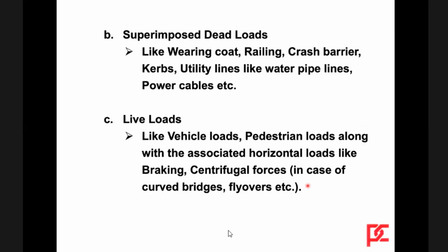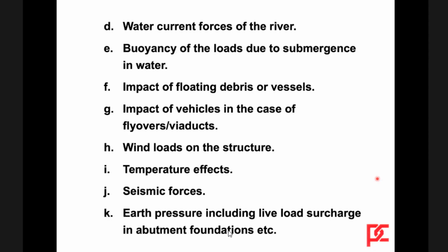Superimposed dead loads like wearing coat, railing, crash barrier, curbs, utility lines like water pipelines, power cables, etc. Live loads like vehicle loads, pedestrian loads, along with the associated horizontal loads like braking, and centrifugal force in case of curved bridges, flyovers, etc. Then water current forces coming from the rivers, buoyancy due to submergence in water, impact of floating debris or vessels, impact of vehicles in the case of flyovers and viaducts, wind loads on the structure, temperature effect, seismic forces, and earth pressure including live load surcharge in abutment designs.